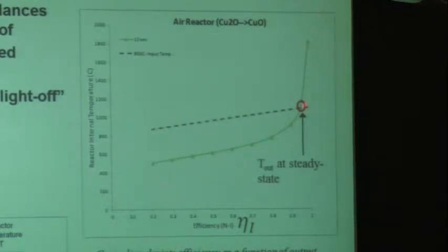This is the plot of kinetics, all right? The efficiency, the amount of conversion, where you actually have the kinetics in there. And what it says is, if I want to get to very high conversion rates, I have to have a high enough temperature to drive the kinetics up with a fixed residence time to get up to that level. This is standard stirred reactor theory, and where those two lines meet, it tells you where the thing is going to operate, right?